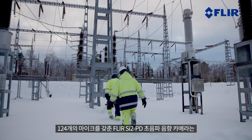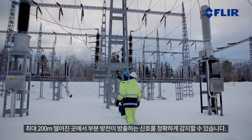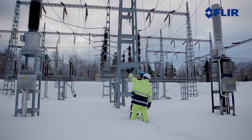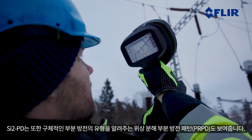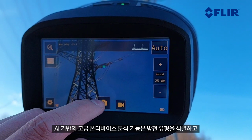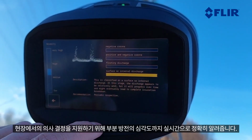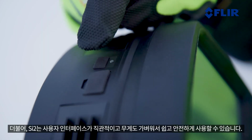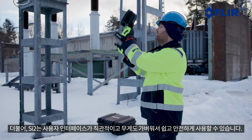With its 124 microphones, the ultrasonic FLIR Si2 PD acoustic imager can accurately detect signals that partial discharges emit from up to 200 meters away. The device then displays the phase-resolved partial discharge pattern, or PRPD, which depicts the type of the PD. The advanced AI-driven on-device analytics identifies the fault type and provides information of the severity of the fault immediately for in-the-field decision support. The Si2's intuitive user interface and lightweight structure make it safe and easy to use.